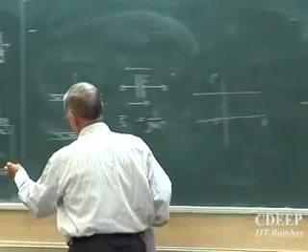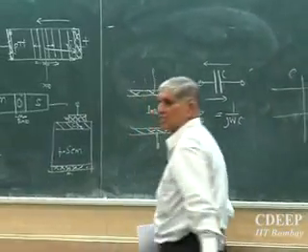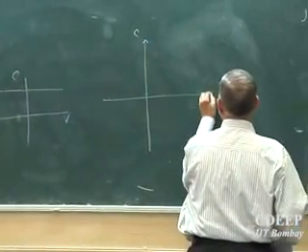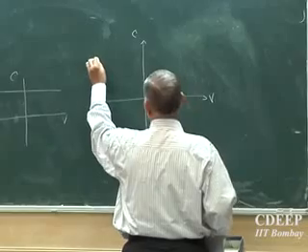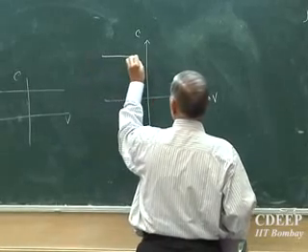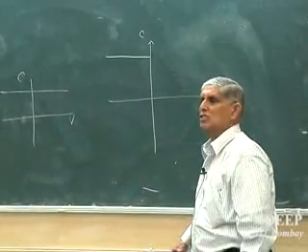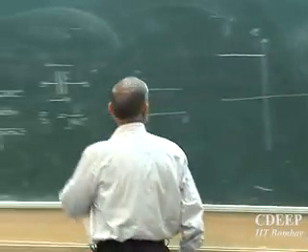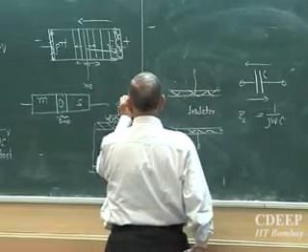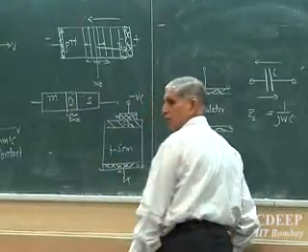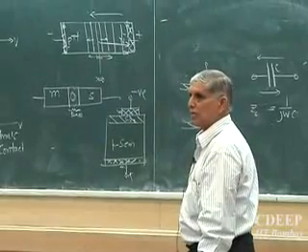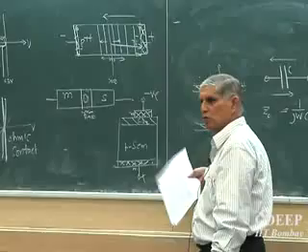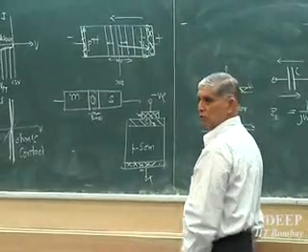Let us say this material is a P-type semiconductor. If I apply reverse bias, or minus voltage, the capacitance is a large constant value. That means the metal top plate is negative and the other side, the oxide and the P-type side, is positive.